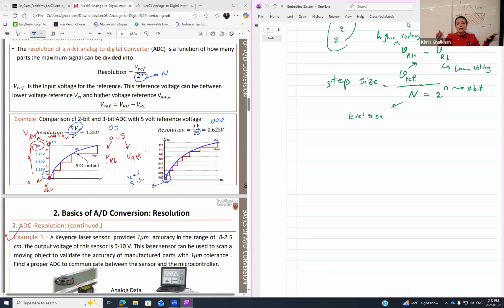When you had it set inside the analog to digital function, it was not able to turn on the RGB on the corner. Then you set it to 0x07, it became 10 bits. You had a more accurate voltage, and you were able to not only, for example, use the pots, change the potentiometer, at the same time, RGB interact. Or if you are looking at the temperature sensor, at the same time, RGB will interact with the temperature sensor or the light sensor, right? That's the impact of resolution.